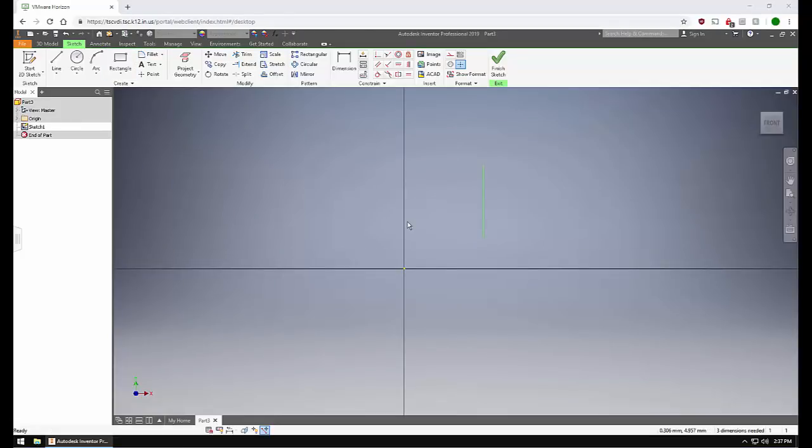Dimensioning tool. The Dimension tool allows you to edit the dimension, or length, of lines. Click on Dimension. Click on the line that you would like to edit the dimension of. Pull out the line and click again. Edit the length and press Enter. Make sure to label. If your line already has a dimension, you do not need to use the dimensioning tool. Instead, double-click on the actual dimension to edit the line. Make sure you label.